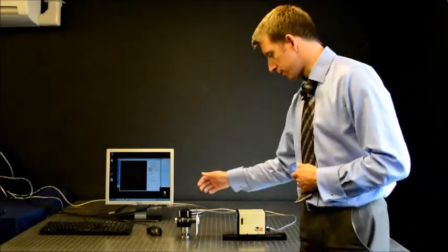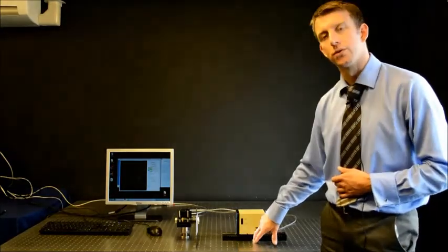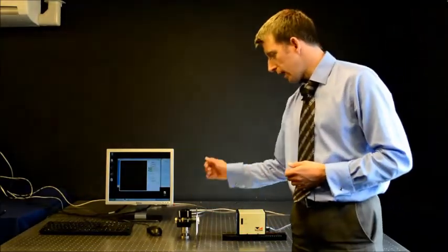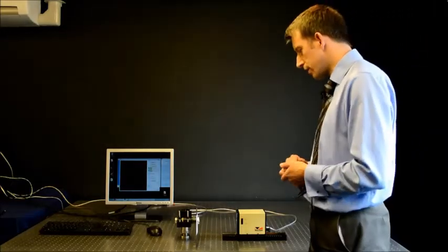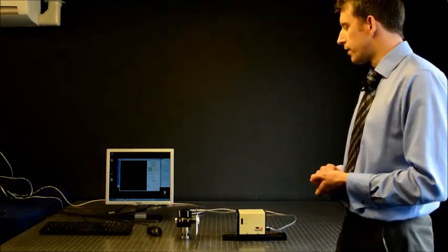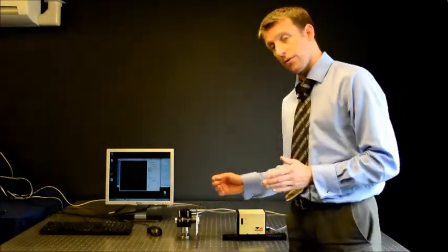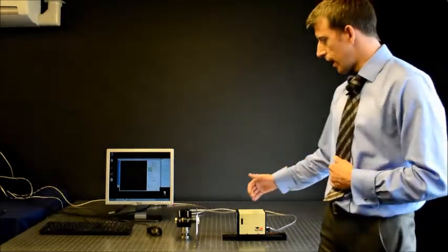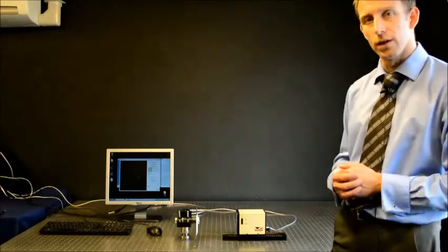The apparent source location is the difference of the position of the PSL Profiler from its initial point at 100 millimeters to its present point. In the case of this LED torch, in the floodlight view, the lens in front of the torch is quite far from the LED, and the apparent source is located relatively near to the physical LED.